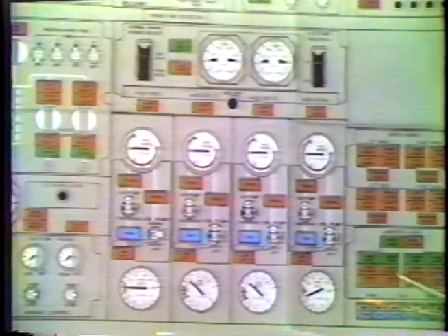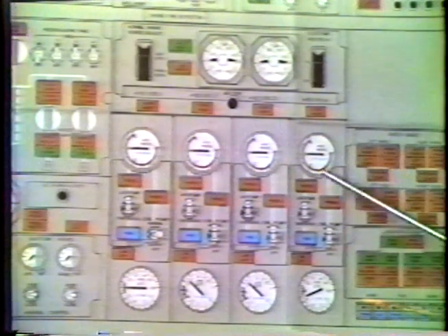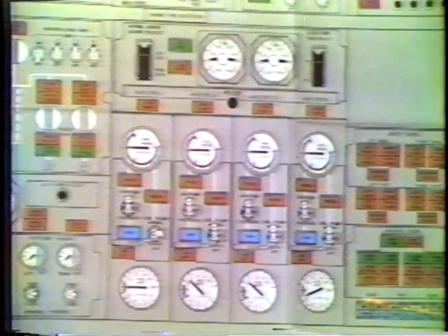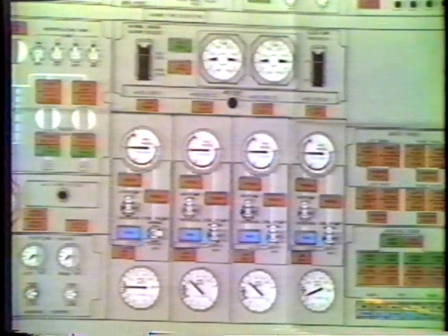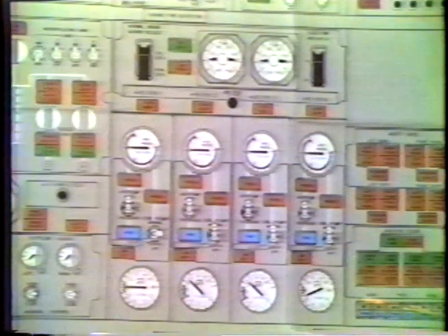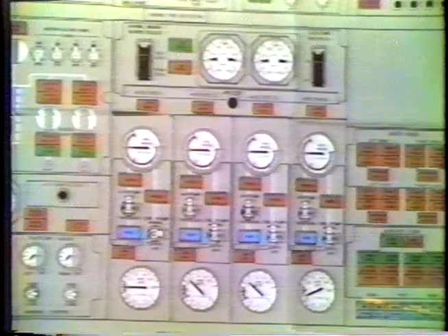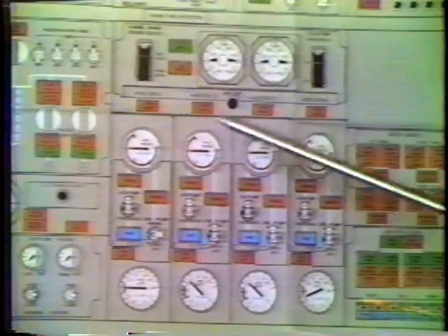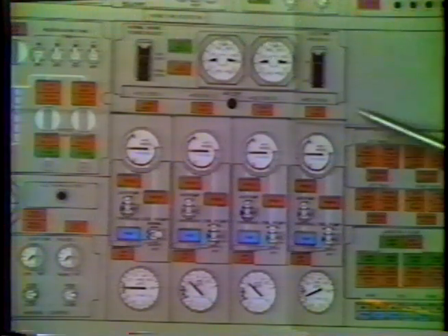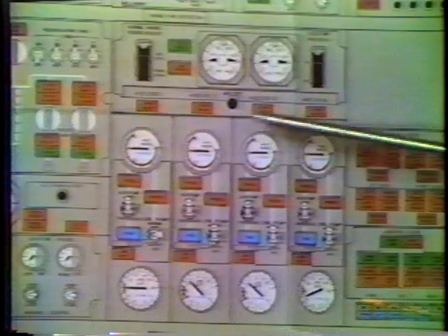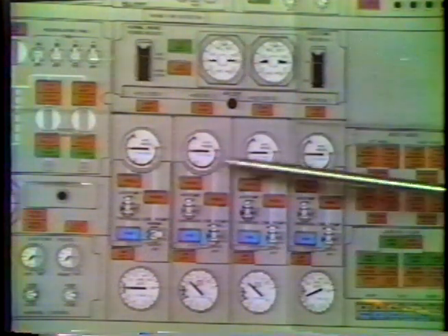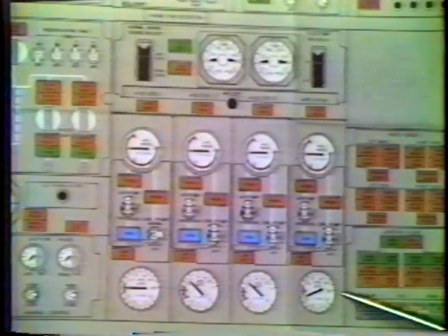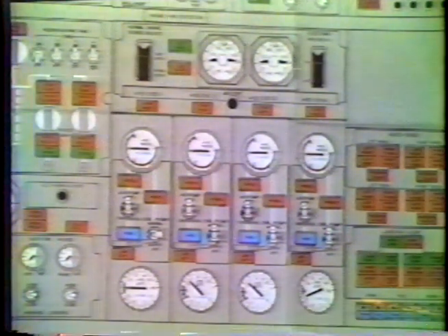The big thing about the hydraulic system is what's on each system. Now, 4 systems are supposed to be totally independent and separate of each other, and what operates each system is relatively easy to remember if you remember one thing. The big items are in systems 1 and 4. The mostly small flow items or flight controls are on systems 2 and 3. And this is reflected in the hydraulic quantity reservoirs. 1 and 4 are somewhat larger than 2 and 3.